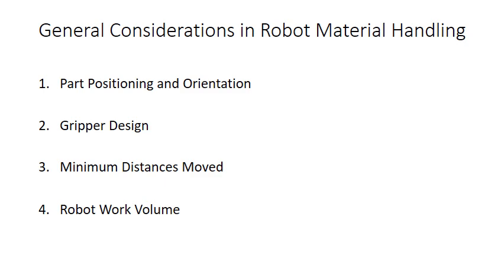Fourth, robot work volume. The cell layout must be designed with proper consideration given to the robot's capability to reach the required extreme locations in the cell and still allow room to maneuver the gripper.